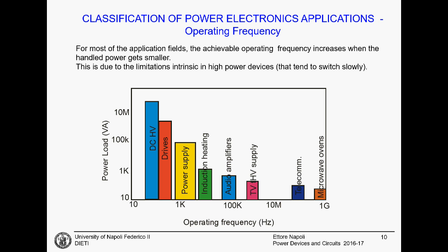But it only works because we can scale everything. We scale the amount of energy for a single bit, we scale the load, we scale the other circuits. When we go with power electronics, we cannot scale everything. Because in the end, if you need to drive an engine, that engine must be big as you need it. If you want to make a train work, this train is as big as it can be. You cannot make it smaller. And this means that the energy is much larger, and the switching frequency can be very, very small.